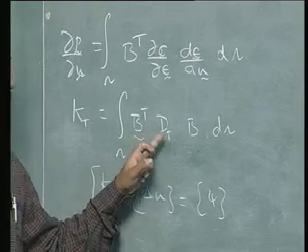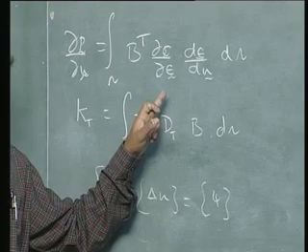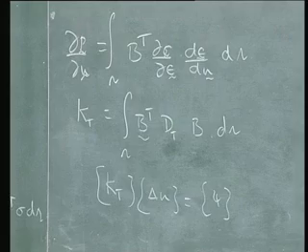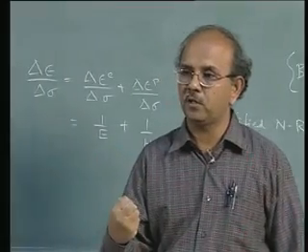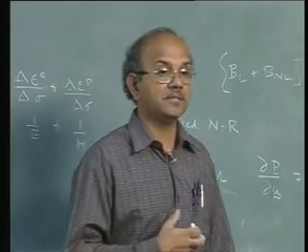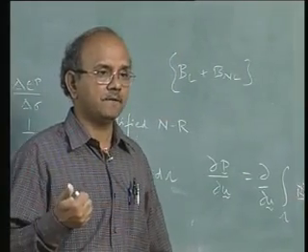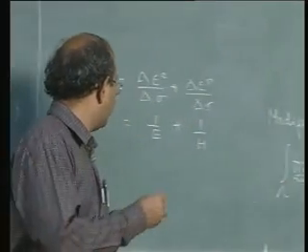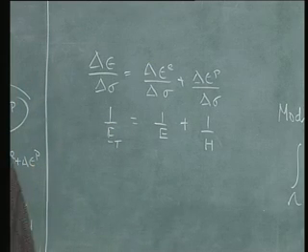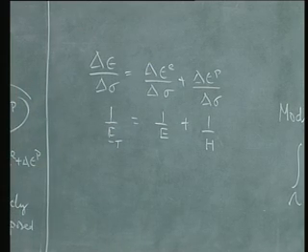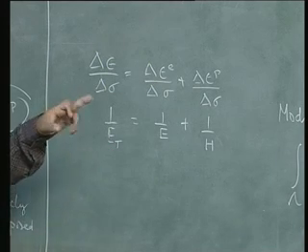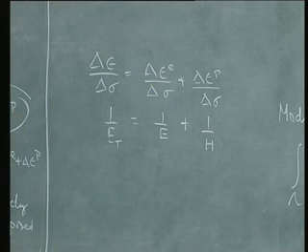And that Dt has d sigma by d epsilon. From a material point of view, though this is a matrix, what goes into Dt is d sigma by d epsilon, and let me call that the tangent modulus. This is tangent stiffness, that is tangent modulus, which I call Et. So 1 by Et is what is called tangent modulus. Yeah, Dt is the matrix from Et.